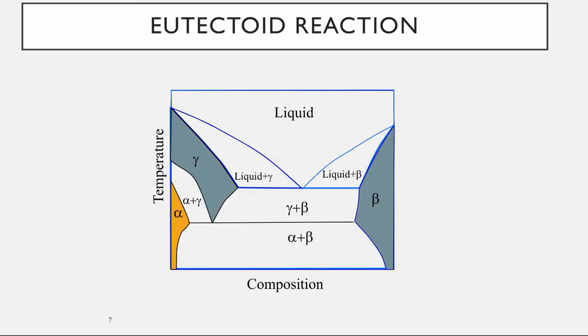So here's an example of the eutectoid reaction on a generic diagram, not even looking at steel. So again, we'd have a liquidus, we have our solidus. That doesn't change. Now, let's say we had a material whose composition was almost all material B. So on this particular diagram, we are still partially soluble, and as the material cools, it would just become this material B holding material A in its atomic structure interstitially, and it wouldn't change what material B is.